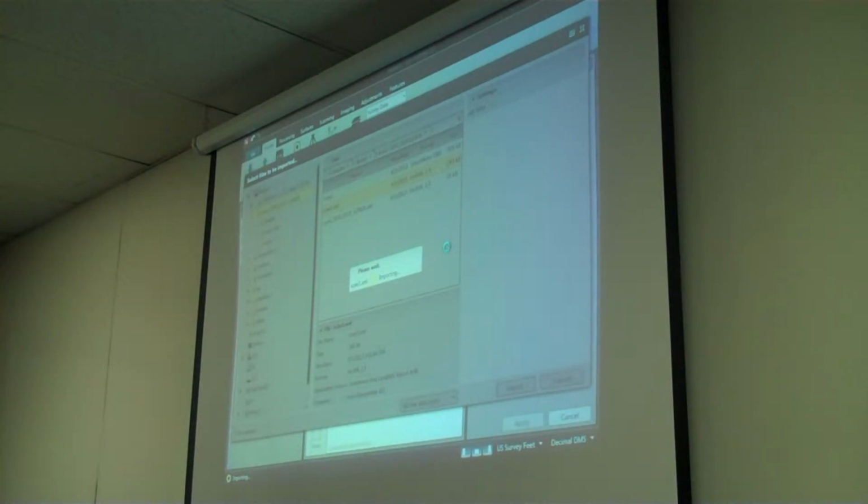This is a roadway project. They did a couple of setups, a couple of scans, captured a road, captured the sides for the ditch, just to give you an idea of how to use it in this application. There are many others. Infinity allows you to do your adjustments. If you decide there's any sort of issue with the setup inside the equipment, you can go ahead and make adjustments inside of this software package and see all those adjacent points change.